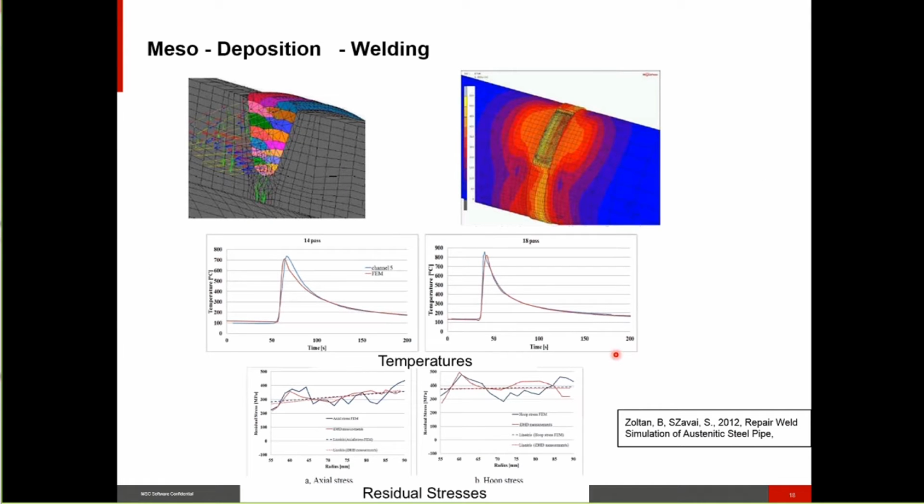And what I want to really convey to you is these are very well established technologies. So while this is not an additive manufacturing problem, it is very similar to it. We're building up this weld region, and in fact, there are 23 layers of material being built up, and each one of those layers is about 1 millimeter in size.